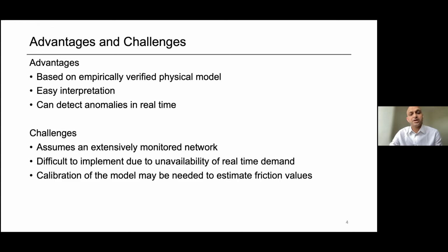One such piece of information is demand. Typically, there won't be any control over how much water is being drawn by individual users for household use, and in fact for industrial use also. There may be an approximate range, but these models don't rely on approximation. They need the exact demand data. We realize those things are critical, and sometimes you will not be able to use these models if the information is not available.